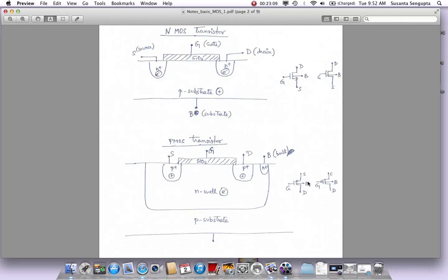In terms of the notation, you have a PMOS which could have an arrow pointing inside. Look how NMOS is. The NMOS, the arrow points outside. PMOS, the arrow points inside, and it's on the top. Same source, drain, gate, bulk connection. And again, what is source and what is bulk depends on the value of the potential there, the value of the voltage there, that is what will define it. From a fabrication standpoint, it's symmetrical. You could swap it, but based on what voltage is attached there, it will change it, and we'll see what I mean by that.